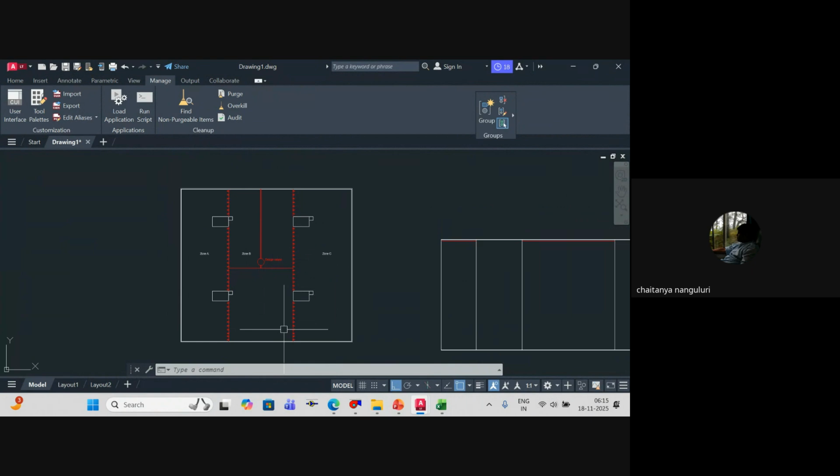Otherwise the fire will spread. But at that location we are having a water curtain. That is only a small location, right? What about the other areas? I'm asking about that location only, sir. We can eliminate it, so can we consider the distance more? Generally, 3 meters we keep as the minimum.